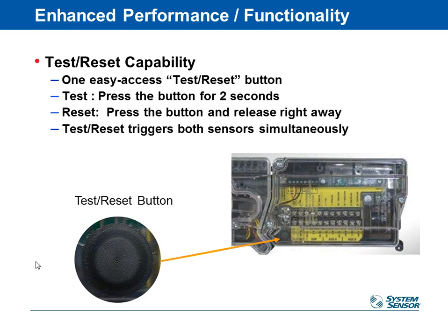The front of these guys also has the test button, so you can test them with a magnet like we used to do, or you can press the button. Either way, your choice. That button also serves as the reset button should you have to come up and reset these guys. After they trip, you do need to reset them manually.